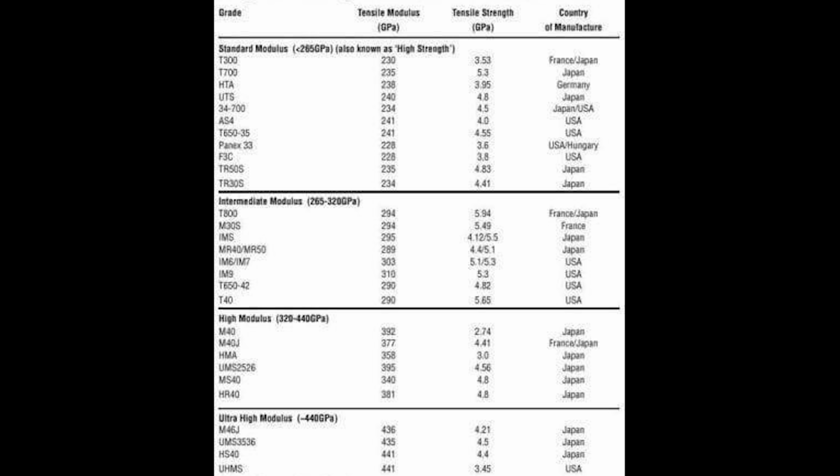Interesting. Yeah, but back to the T300. There's nothing wrong with it. It's just really old, and far better fibers exist right now. But it does not exist in 3K. But this means that if you read that, oh, this part is made out of 3K carbon fiber, it means that it's most likely made out of T300, and that is, yeah, the weakest. Oh, I see. So it's synonymous with T300. The 3K moniker is synonymous with T300. Okay. Yeah, more or less, yes.